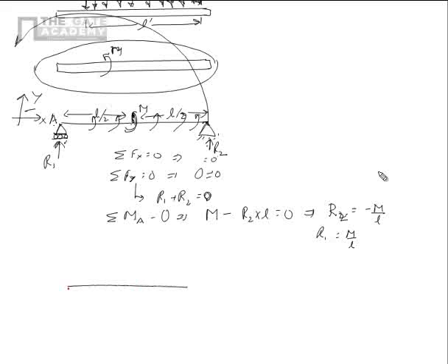That's another interesting scenario. Let's take the same simply supported beam. So it provides reactions like this. This is R1, this is R2, this is H1, this is a pin support, and at the center we have distributed load of intensity W acting over the length of L by 2 totally. So this is L by 4, then this till center is L by 4, again L by 4 and again L by 4. So at the center half of the beam length, this load is applied.